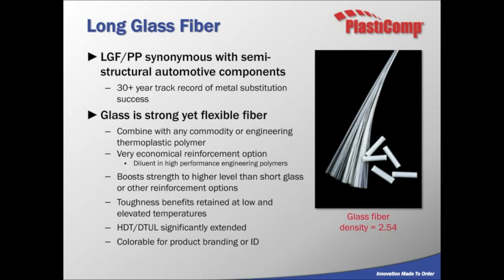So with our glass reinforced long fiber materials, you will see the same impact values at -40 as you do at room temperature. You extend the heat deflection temperature significantly beyond base resins by using long fiber materials, and then they're also colorable for product branding or ID.